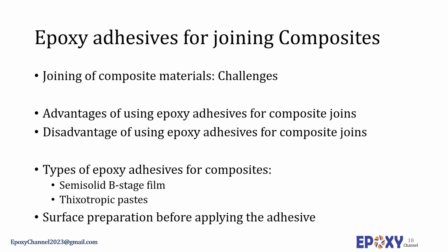In some cases, a primer may be used to coat the composite before the adhesive is applied. Another technique, a peel or tear ply, is used on the composite sheet as the outer layer of the composite during its production layup. This outer ply is then peeled away just before bonding, which fractures the resin's matrix coating and exposes a clean, fresh, and roughened surface for the adhesive. This method is fast and eliminates the need for solvent cleaning and mechanical abrasion.